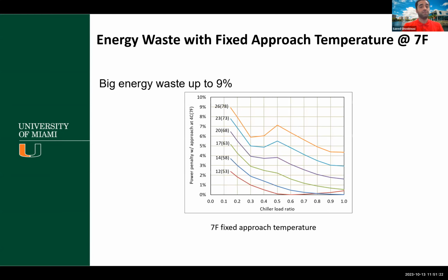Another conventional approach was a fixed approach temperature at 7 degrees, and similar to the last slide, we applied it in our system. From the simulation results, we see a big energy waste, less than with fixed leaving water temperature, but still up to 9% of the total system energy consumption can be wasted using the fixed approach temperature, which is not optimal.